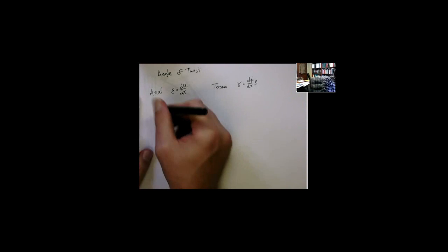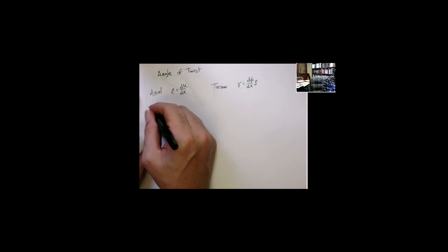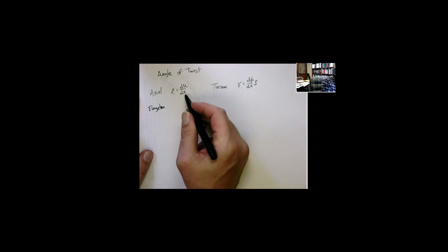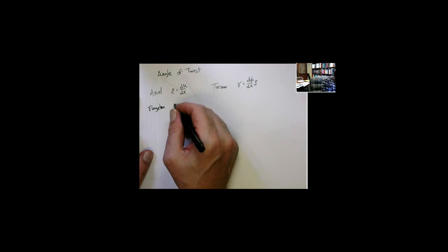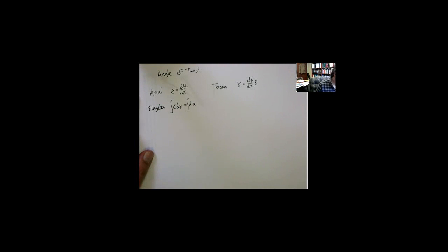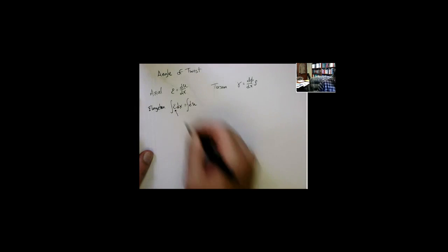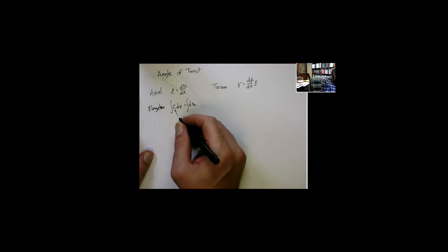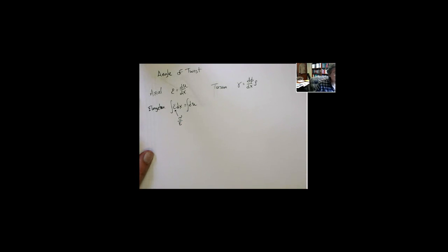Now, in the axial case, we then wanted to get the elongation. And we got that by multiplying the strain by dx. Integrate both sides, get u on the left-hand side, and we substitute in for the strain in terms of the parameters we know a little better, the internal forces and geometry. So we know that the strain is the stress divided by Young's modulus, right? It's Hooke's law. And we know that the stress is the force over the area.